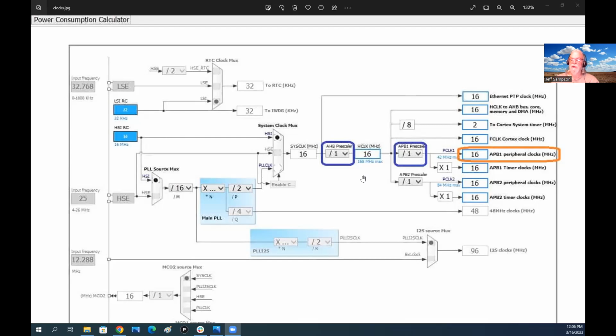I don't know what the clocks are set at right now. So I was thinking I might be able to cut the clock configuration stuff out of the big ST micro IDE and dump it into a function called Black Pill fixed clock. Then when I start up in my setup stuff, I just call the fixed clock function, and then I can set it to whatever I want. So it'll bypass all the stuff they're doing. I don't know how it's going to affect other stuff on the board if I start changing the clock speeds, but that'll be a quick test to see if that does indeed fix the problem.